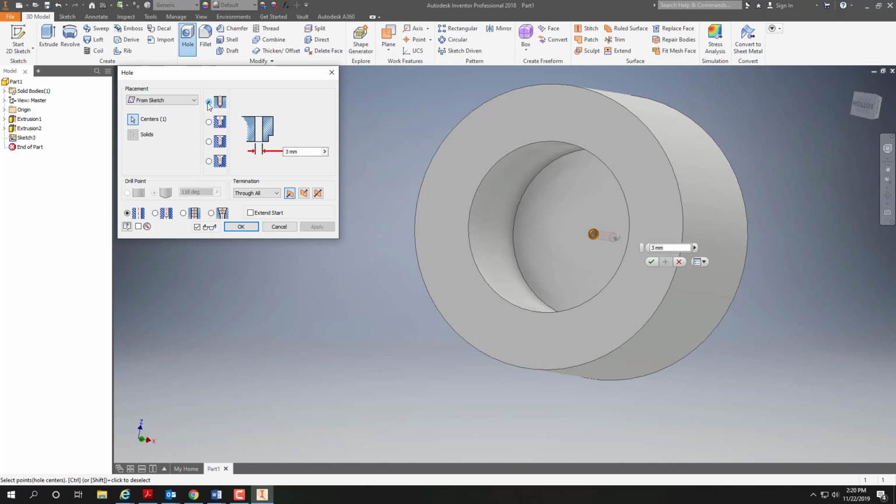All right. Now, the diameter of the hole, if we take a look at it, the note says M24 by 3. Now, the M tells you that it's metric. The 24 will come over here. That tells us the diameter. Now, notice it changed right here, okay? But there's a pitch. The pitch is 3.